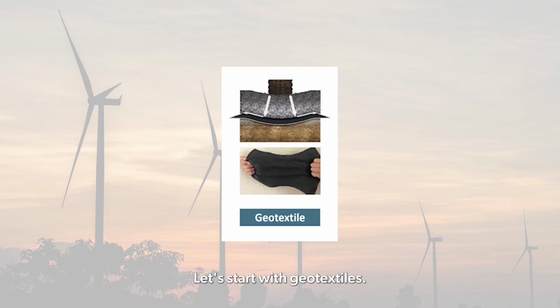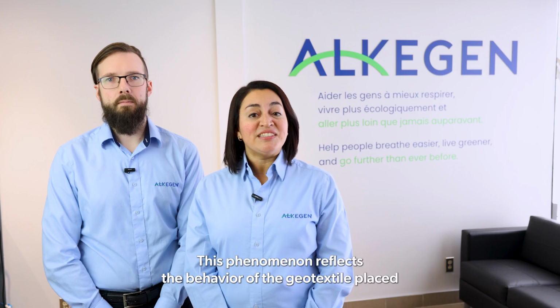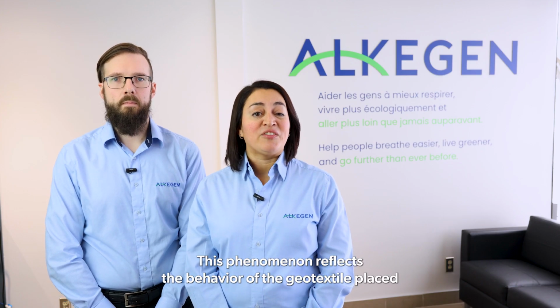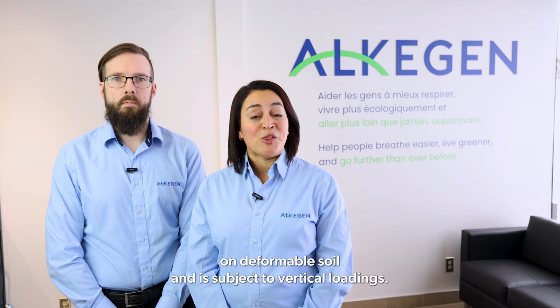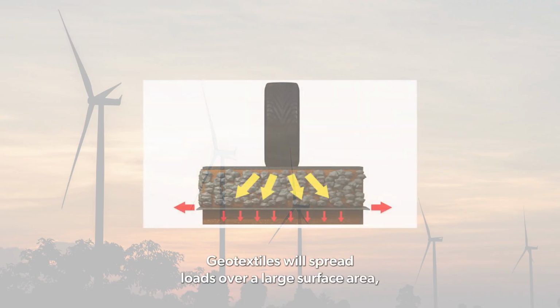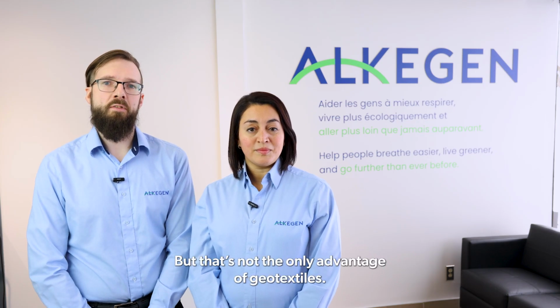Let's start with geotextiles. Geotextiles are very useful for first-level stabilization solutions as they offer a stabilization mechanism known as the membrane effect. This phenomenon reflects the behavior of geotextile laid on deformable soils and subject to vertical loadings. Geotextile will spread loads over a large surface area, thus increasing the shear strength of adjacent soils and reducing the risk of rutting. But that's not the only advantage of geotextiles.